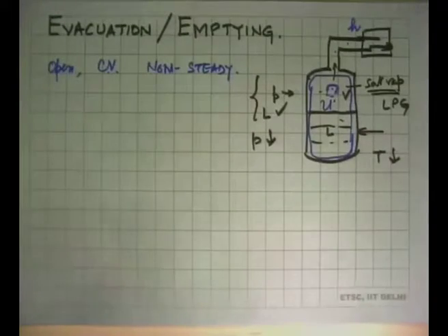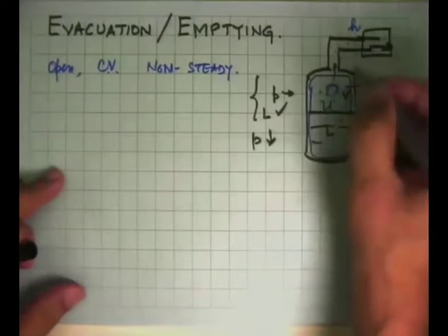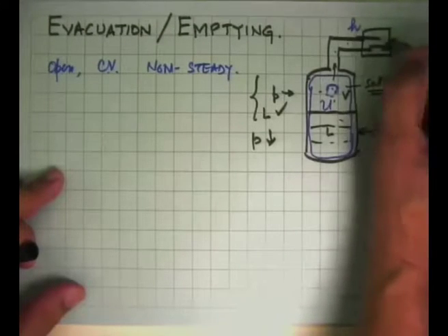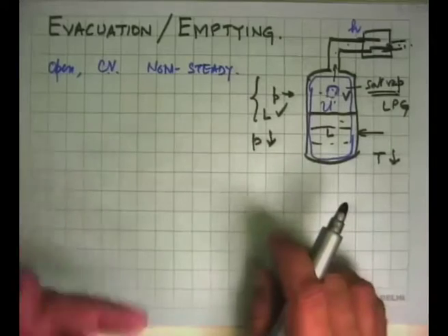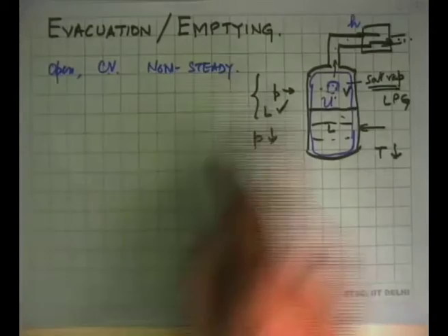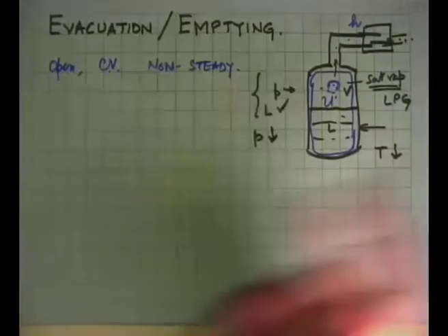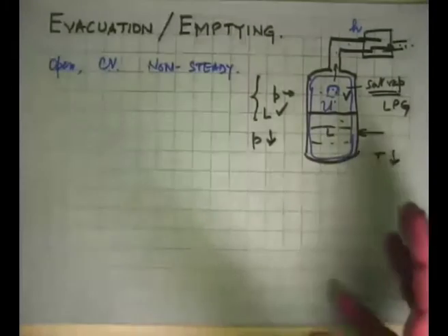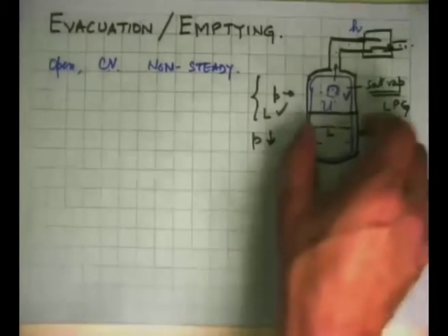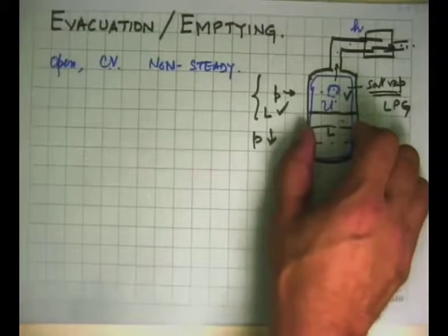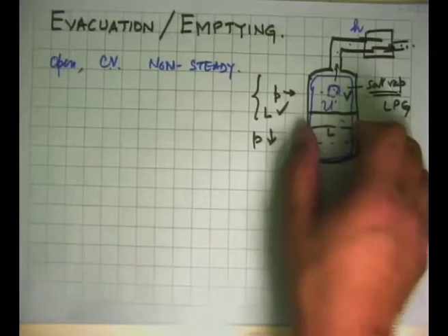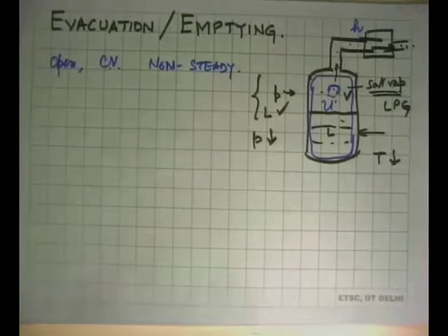So the pressure regulator is designed for the fact that butane will come out at a certain pressure, it will throttle it and produce a pressure which your LPG stove actually wants. Analysis of this proceeds exactly the same way as before, so I will not repeat it, but you can write the full equation. Again, make similar assumptions that heat transfer is 0, work transfer is 0, kinetic and potential energy changes are 0, and simplify the equation and solve it.